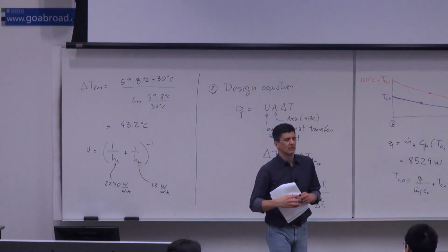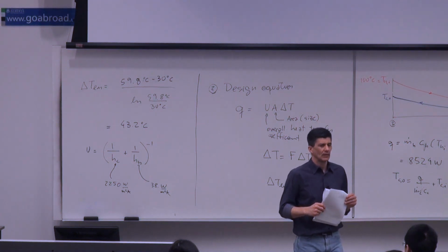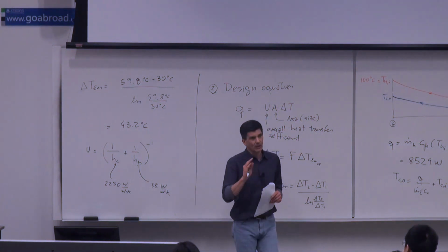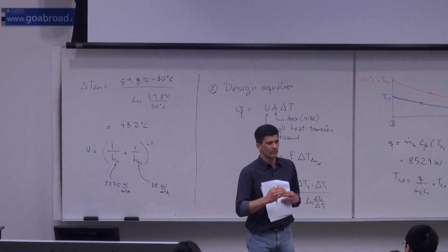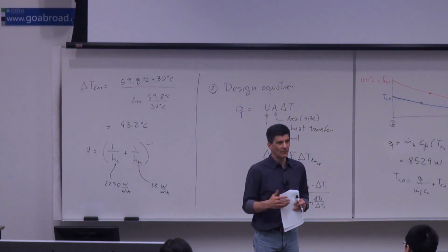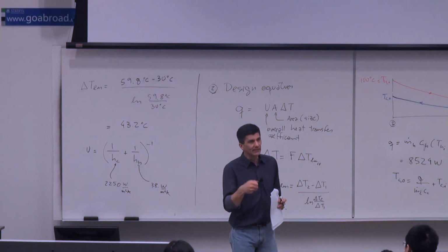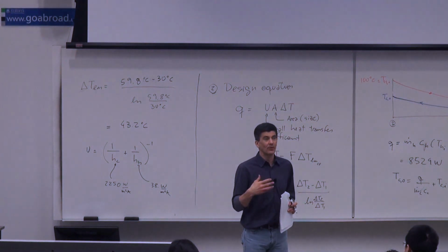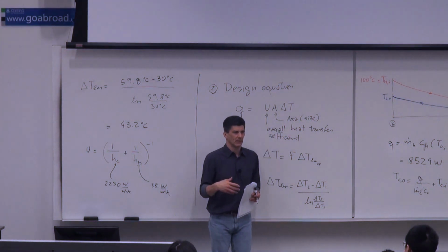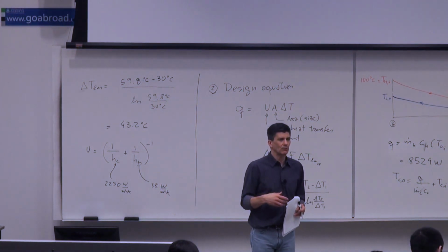Yeah? So, like fouling, you have to account for what makes. Oh, you can put fins in your oil if you want. Now, that's a design question for which I don't have the straight answers, but I can tell you some things I heard about. Fouling is a very foul thing, right? And so it's when you clean them, right? If you have fins, it's very difficult. So you would seldom want to put fins on the oil side, right? But you can do things. You can try to induce turbulence.